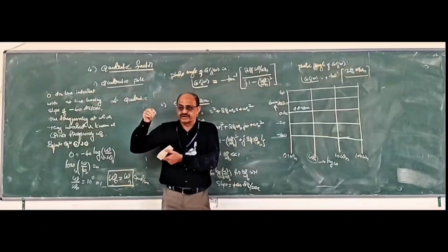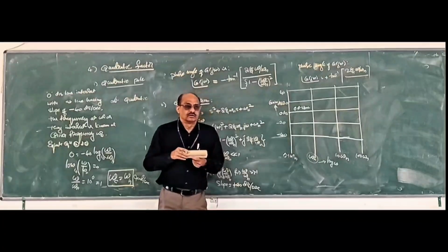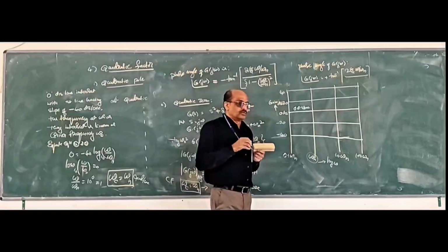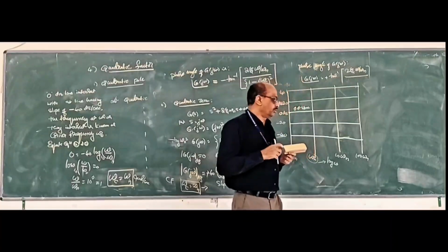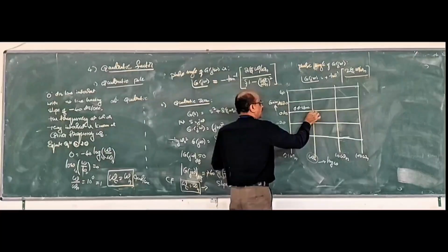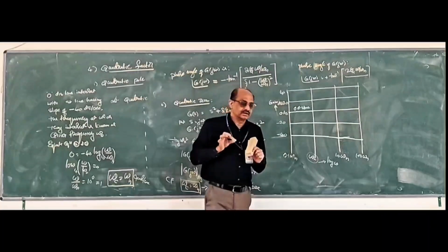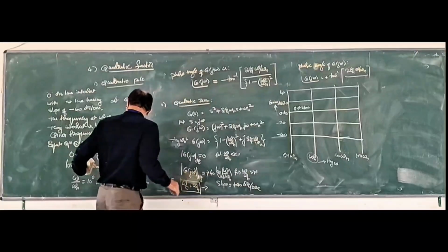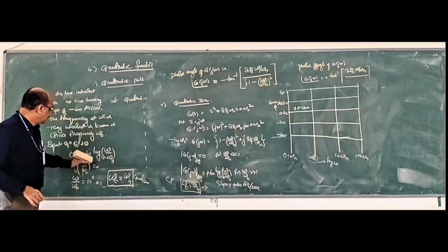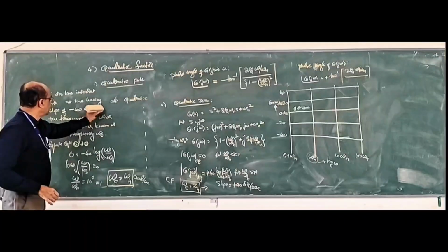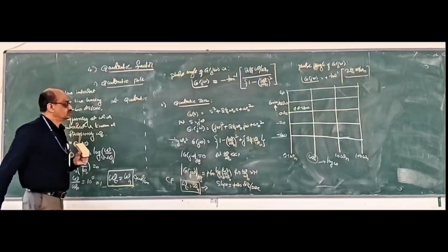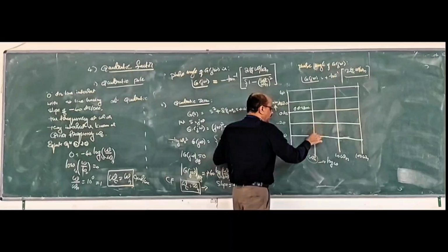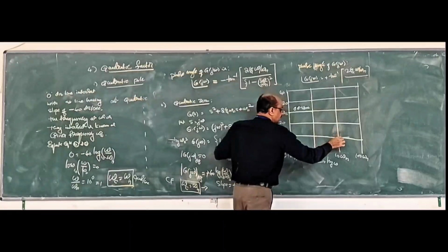The same thing you have to identify in the equation where it is given, to sketch the Bode plot. The 0 dB line is drawn, and then the slope of the line is minus 40 dB per decade. How to generate it? From this one, minus 40 down, and 10 times that frequency is this.